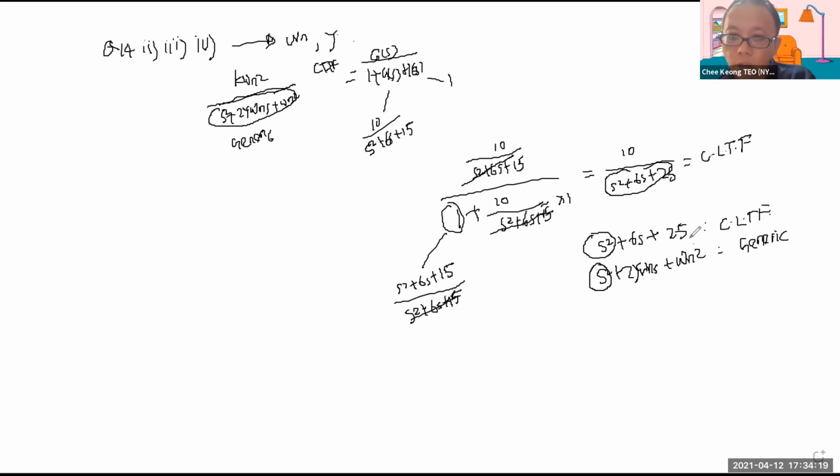So now you want to find omega n, you take the last term, right? In order for it to be equal, all terms must be equal. First thing, your s squared must equal s squared first. If there is a number here, then you cannot equate, right? So you must divide first. You must normalize everything to s squared first. So now, for this term, we can see that omega n squared is equal to 25. So what is omega n? Omega n will be the square root of 25, which gives you 5 radians per second.